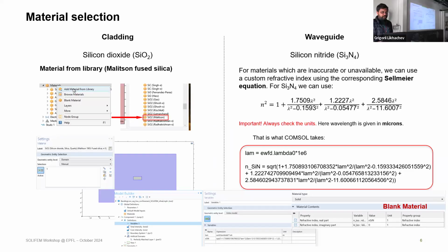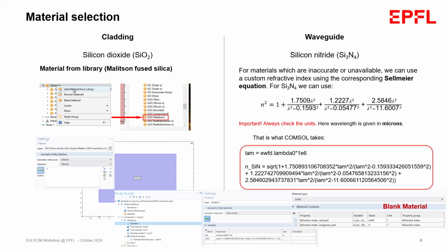Here also I think Zeru must have mentioned that in the axial symmetric model of COMSOL, your effective index is actually multiplied by the radius, and still it calls itself the effective index. So you need to be careful that in COMSOL, n effective multiplied by r is called the effective index. It just multiplies by r and still calls it an effective index in the axial symmetric model.